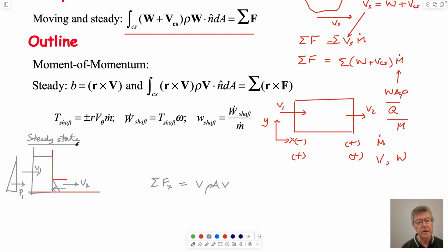And it's steady state because the same amount is flowing in as flowing out. If that's the case, then the product of these two terms is a constant times a mass flow rate, and we know that at steady state mass flow rates sum to 0. Mass flow rate in equals mass flow rate out. That's what that statement is. And so a constant multiplied by that just changes this expression to this. It drops out this term because the velocity into the system is also equal to v, because it's not moving. So steady state and static.